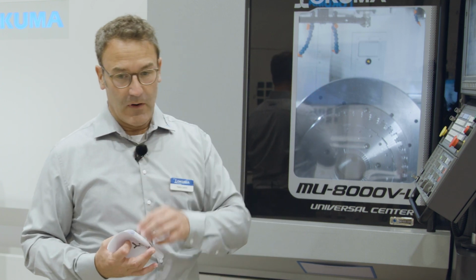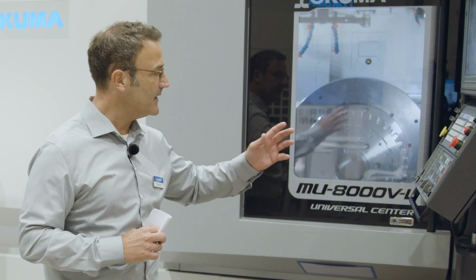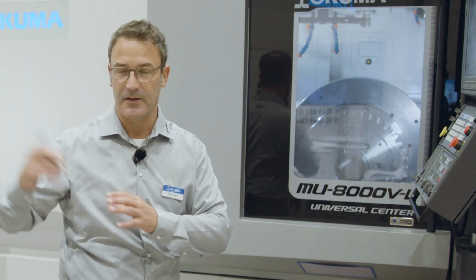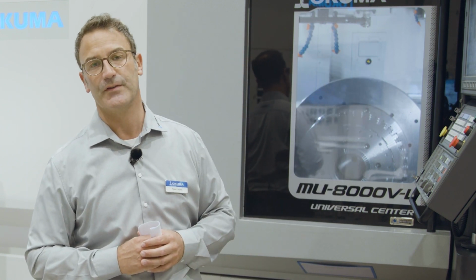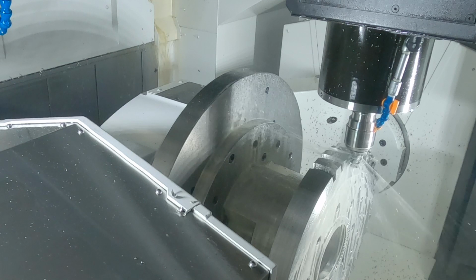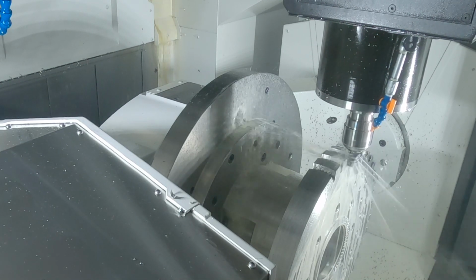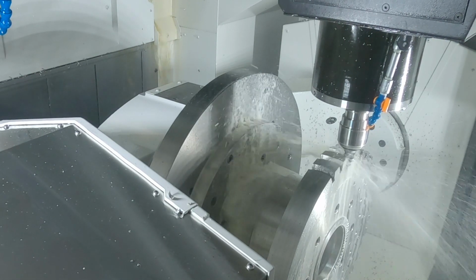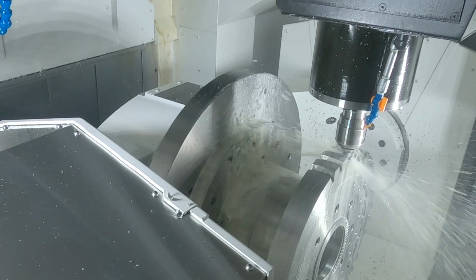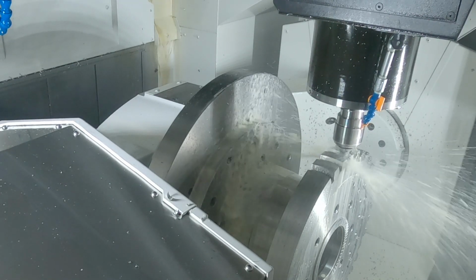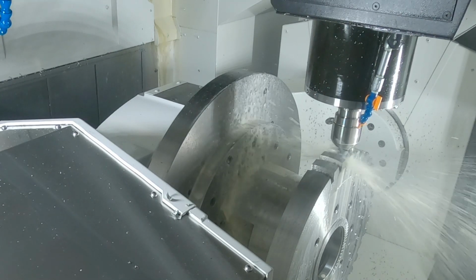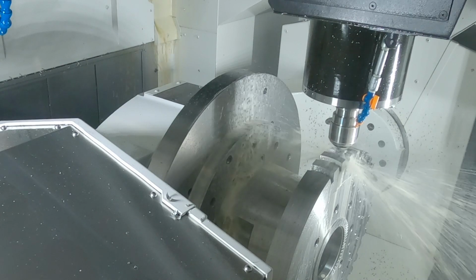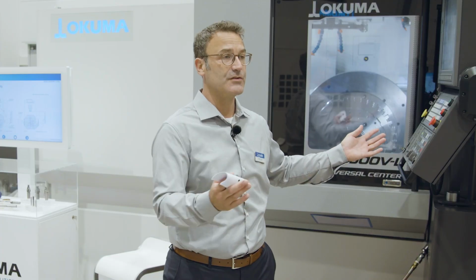What we also have in addition for the intelligent technologies over here is the thermo-friendly concept, which we also heard about on the opposite machine, the Multus U4000, and we will also hear about on the Genos M460-V. We have certain temperature sensors in dedicated areas, which recognize the temperature change, and according to the change, the machine automatically makes some resettings and calibrations, so that the machine keeps the micron level in the part. Even if your operator shortly goes to the toilet or goes for a smoke, and the machine stands still for 10 or 15 minutes, the machine is still as precise as before, which is a huge benefit for you.